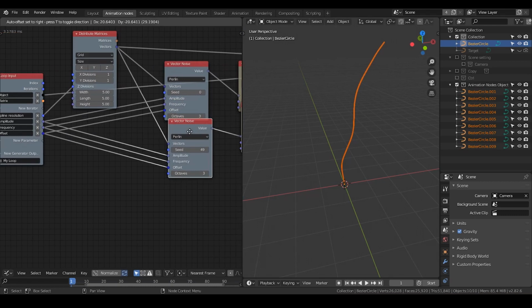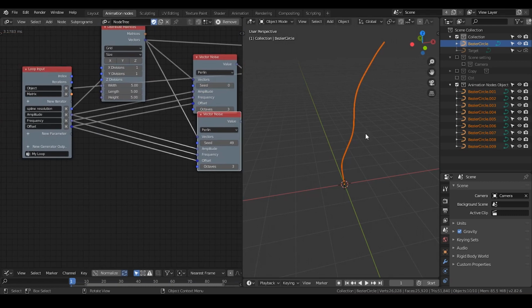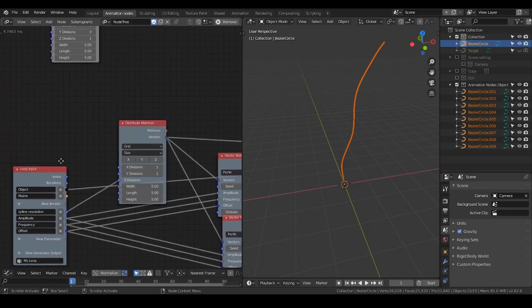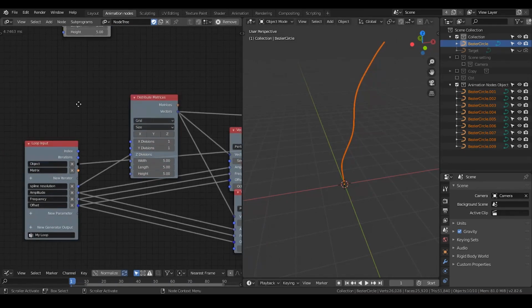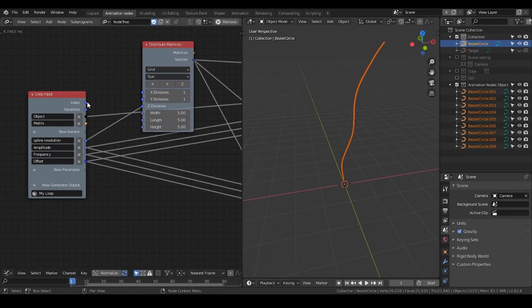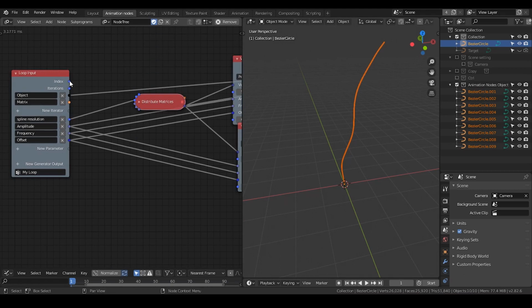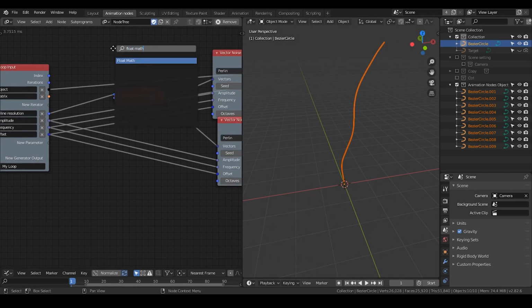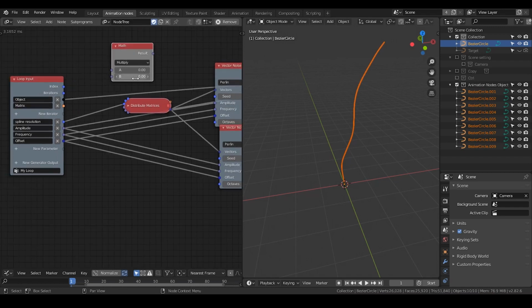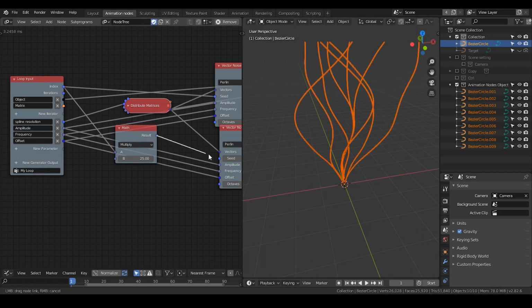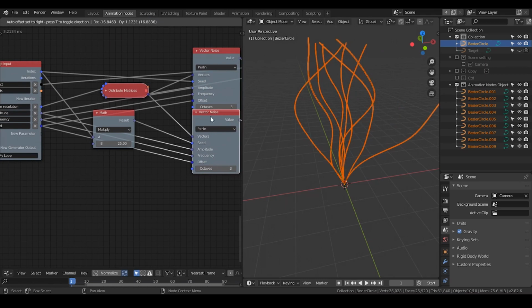One thing I have to say firstly is we're going to change the seed for each spline. To do that, I'm going to use the index, because this loop will be run 9 times because we have 9 grid points to run, or 9 objects to create. For each time the index will change from 1 to 8. So this is the principle. I'm going to use this number to change the seed. So let's add a float math. Let's just multiply by like 25. So one index goes to one seed, and the others go to other seeds. That generates different seeds for them.